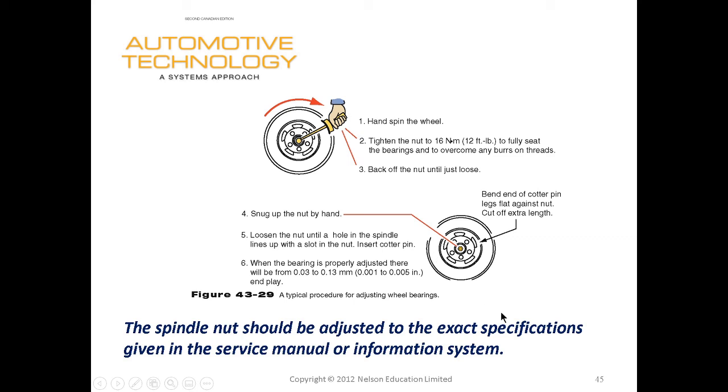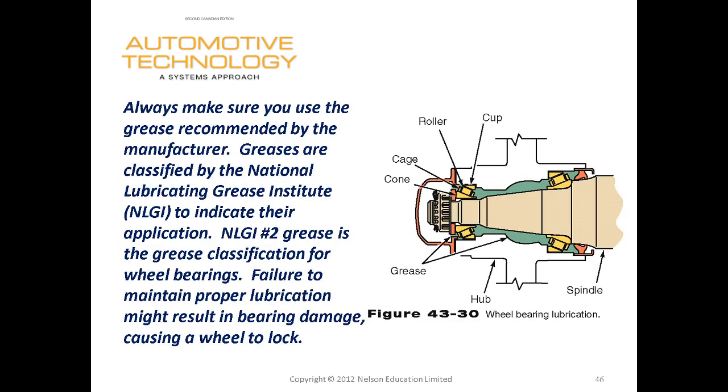Adjusting wheel bearings, this is important. So always go by manufacturer specifications, but generally we want the hub to not have very much end play. So what are their specs here? They're saying 1/1000th of an inch to 5/1000ths of an inch. Kind of a side profile showing our wheel bearings here. So our spindle, our inner bearing and our outer bearing. Generally the inner bearing is larger diameter. I'm not entirely certain why. Probably takes more load.